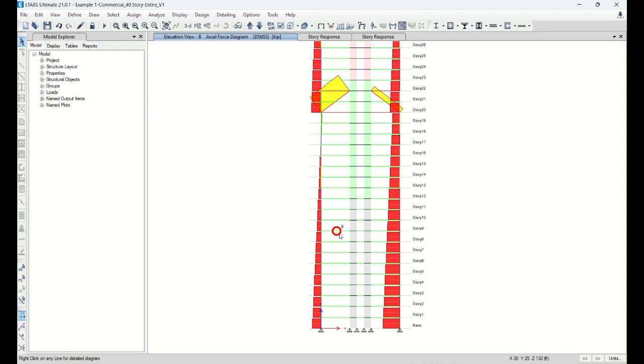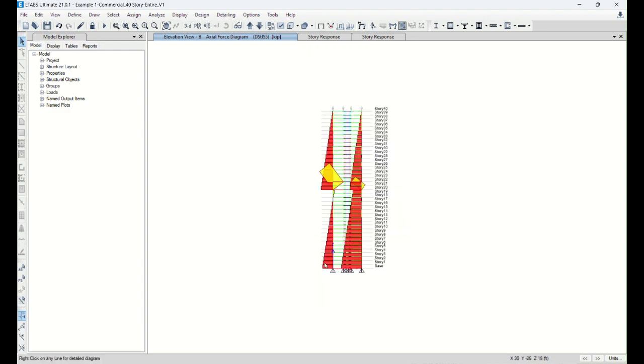Probably here you can see all the axial force distribution like this, the combined effect due to gravity and lateral. Still, we have some kind of issue on our gravity loads because the bracing is holding up, so we underestimate our actual forces, right? If we use this model as it is, obviously we may end up under-designing the column.